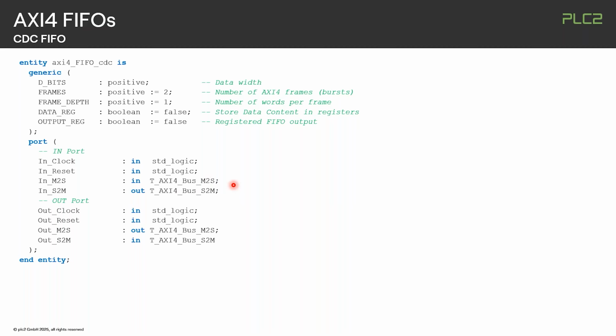And we can therefore limit the number of ports in our port lists here to just 2 signals. Then, of course, we need the clock and the reset signal in here as system clocks. In case what I'm showing here is a CDC variant, we also need the clock and reset from the output port side, from the consumer side, and this is all we need to connect.